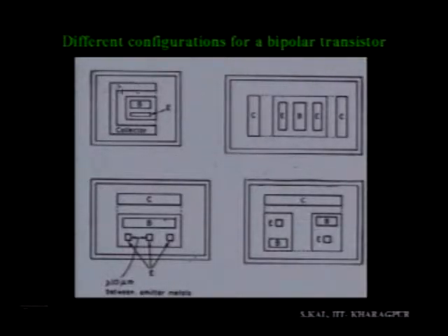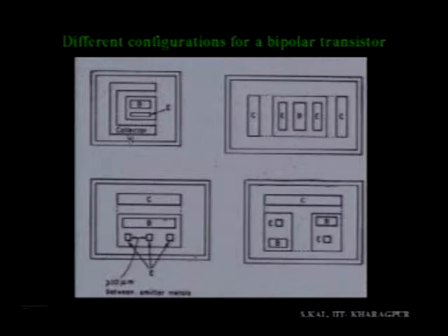This is the diffuse collector region, deep collector region, for example, and that also helps the wiring, or the metal wiring, meaning the routing. For example, for some transistors you can take contact from this side in this direction, for some transistors you can open the contact window on this side and take contact in this direction, and for another you can take contact in this direction.